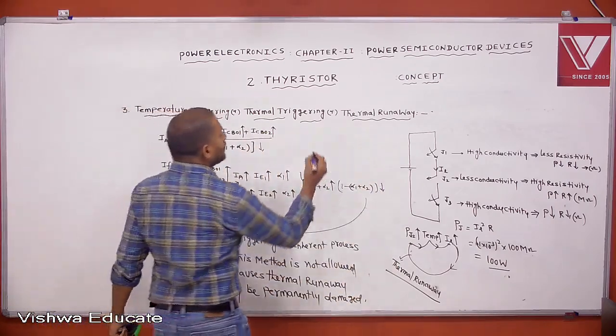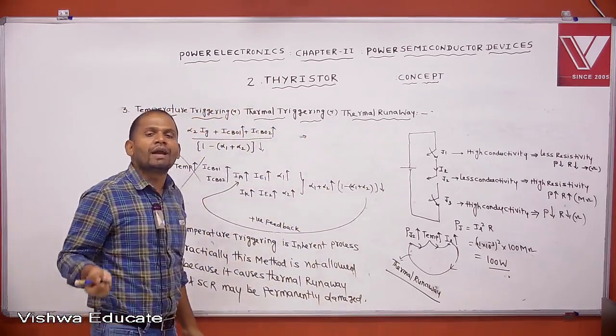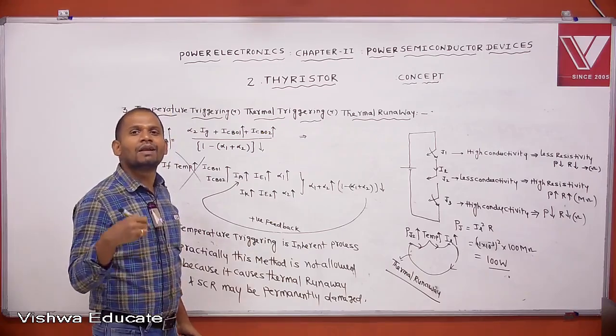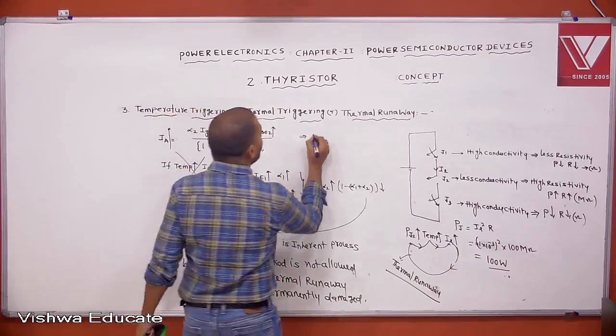The point to remember: practically, SCRs are mounted on heat sinks in order to eliminate thermal runaway or temperature triggering.